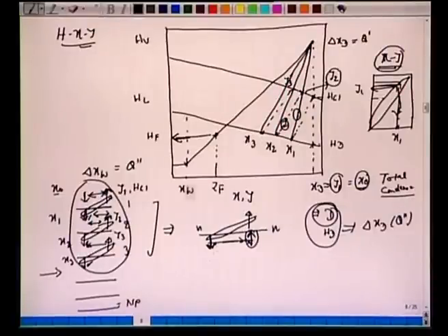Why is it common? Because the difference between the molar flow rates of the vapor arriving at that plate and the liquid leaving that plate is a constant. Alright, the enthalpy of the vapor which reaches this plate and the enthalpy of the liquid which leaves that plate is also a constant. So by applying this mixing rule, we have obtained this common point here. So whatever calculations we do here, we are also getting physically on these stages. If we start from the liquid, we go to the vapor by operating line, then from the vapor to the liquid by tie line, then from the liquid to the vapor by this operating line. Alright, so our movement stage-wise is like this.